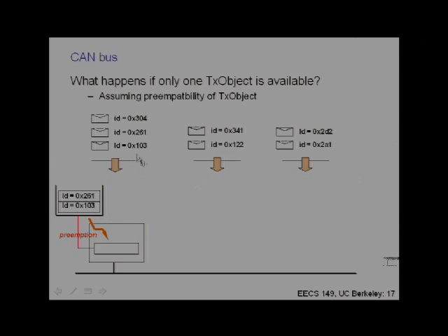But we would have expected, of course, that because they arrived at the same time, 103 gets to go first. But that didn't happen because there was some finite amount of time required for message 103 to preempt this message and then get copied into the buffer here. And by the time all that happened, 122 got transmitted on the bus. Okay? So you can have priority inversions.